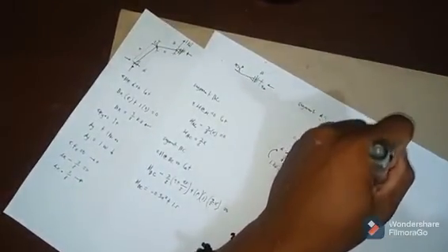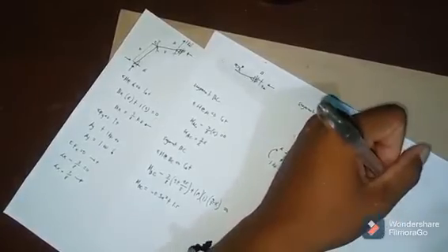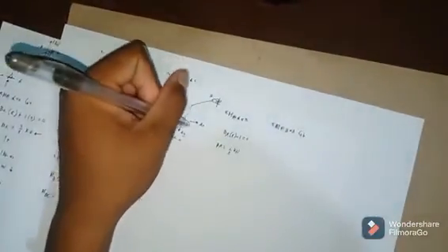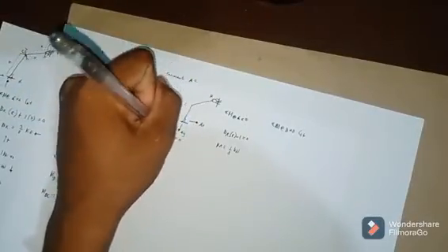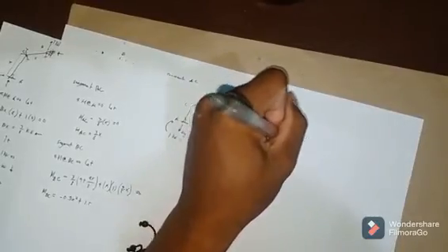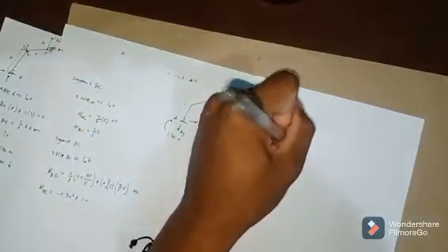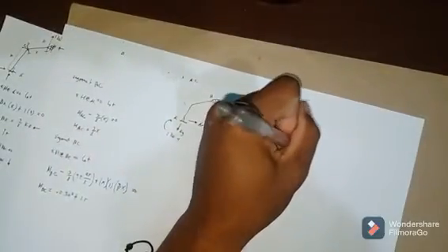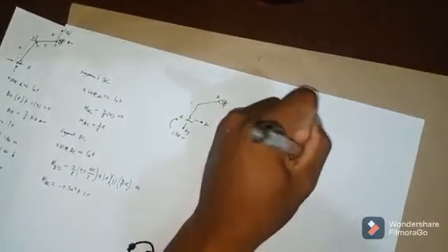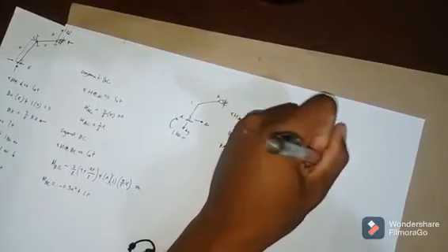And then summation of moment at B is equals to 0. Considering counterclockwise positive, if you take the moment here, 1, which is rotating clockwise, so negative 1, plus 1 over 8, our Bx, times the perpendicular distance, which is 3 plus 2, 5, minus AY times 3 is equals to 0.